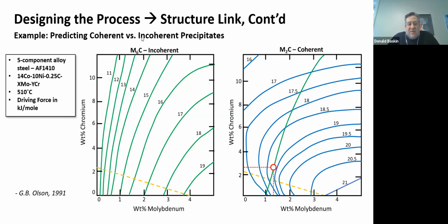They originally got into the business of making high strength tubing, I think because they were making oxygen bottles for Mount Everest climbers, who needed a light, strong, high strength to density ratio canister to hold oxygen so they could carry as much oxygen up mountainsides as they could possibly get. But the 853 alloy is an air hardening alloy, and it will form martensite, I believe, by air quenching. They call it an air hardening steel.